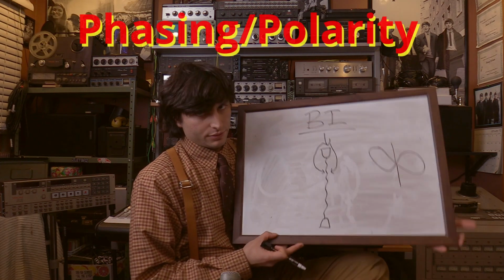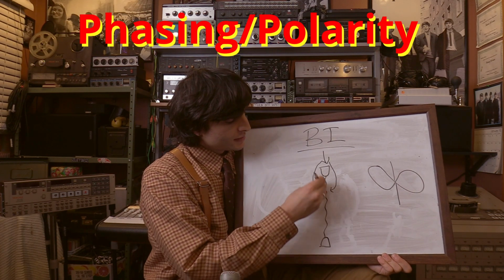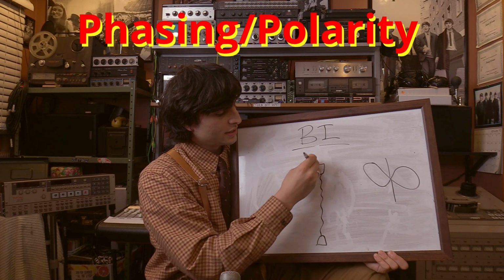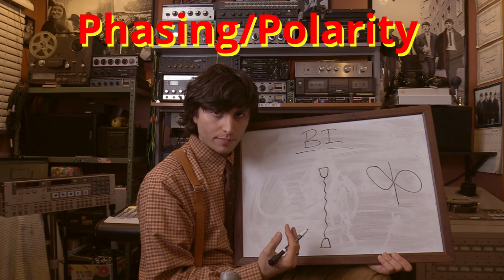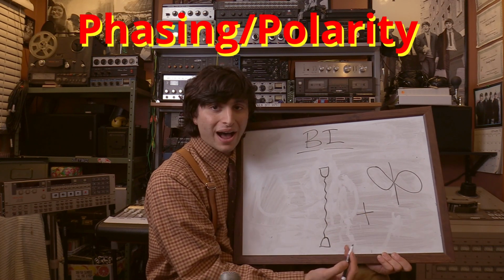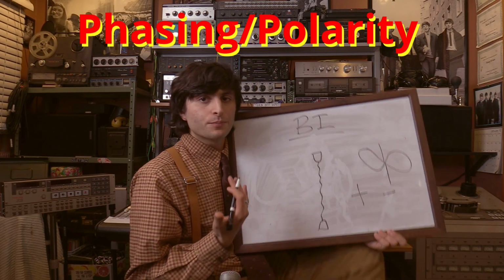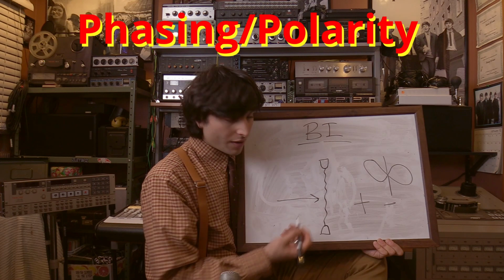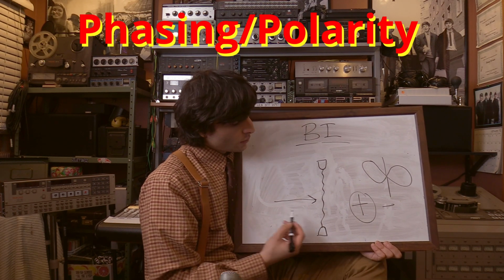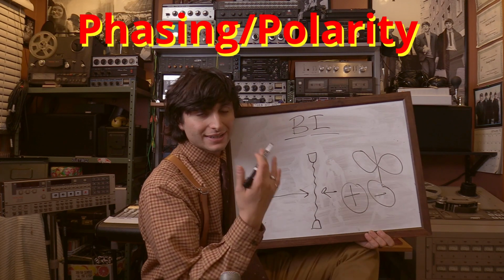Something really important to think about when you're placing bidirectional microphones in a room is that depending on which side of the ribbon the pressure wave is going to be coming from, you are either going to be seeing a positive electric signal or a negative electric signal. If the pressure wave is going to the front of the microphone, that is when you get a positive voltage. When the pressure wave is coming from the opposite direction, this is going to give you a negative voltage.